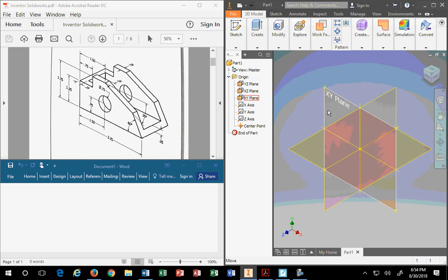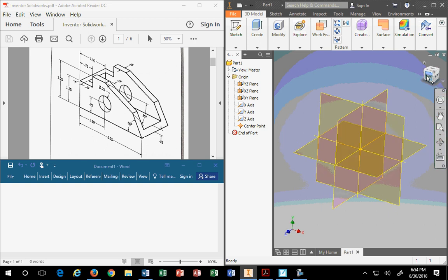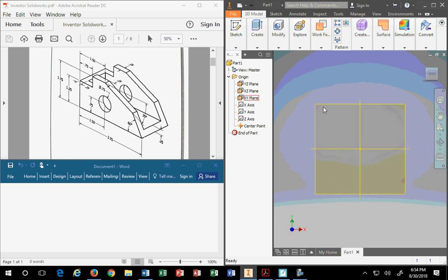So you want to know where you are in space. This is what it sees as the front. What's the front? The XY plane. Write that in your notes. The front is the XY plane. Inventor chose not to give the plane the name of front view because defining a name of that nature also defines to us a perspective, correct?